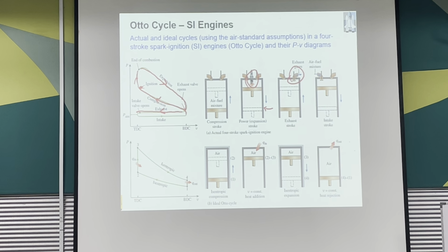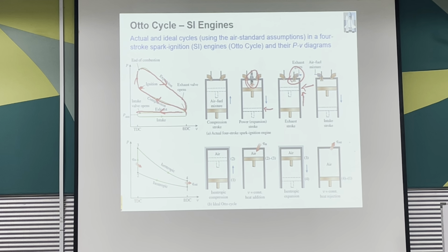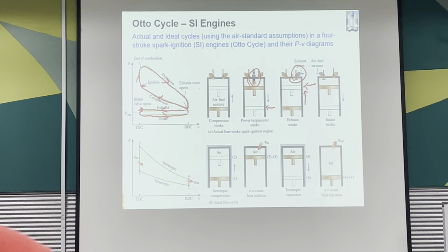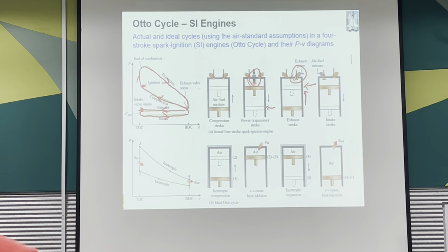Then when the crankshaft reaches the TDC, the exhaust valve will close. Then the intake valve will open, and it will take in more air fuel mixture. Then the compression stroke will happen again. So this will go on in the cycle. You can see here, this is my intake valve open, then again this is the intake, where when you take in the air fuel mixture, at the same time it will push the piston back down to the BDC. So that is how it all goes.